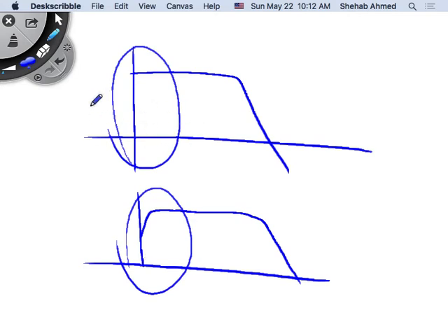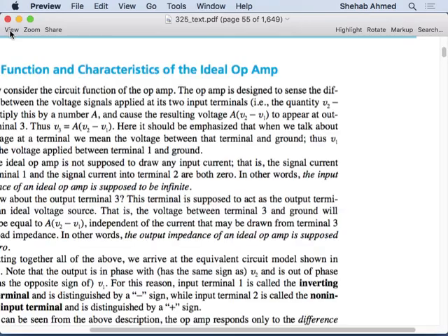But this is just a fact of life. We will have to live with the fact that these are DC coupled amplifiers because these are typically on integrated circuits. And we said that for proper capacitor coupling, you would need a large capacitor to be able to do this capacitor coupling and attenuate the signal. Right? We discussed that last time. Op-amps are built on integrated circuits. You do not have the luxury or the real estate on the chip to build a large capacitor. So that's why it's a DC coupled amplifier. And as we said, it has infinite bandwidth, infinite gain, input impedance equal to infinity, output impedance equal to 0. So all these are interesting characteristics of the op-amp.